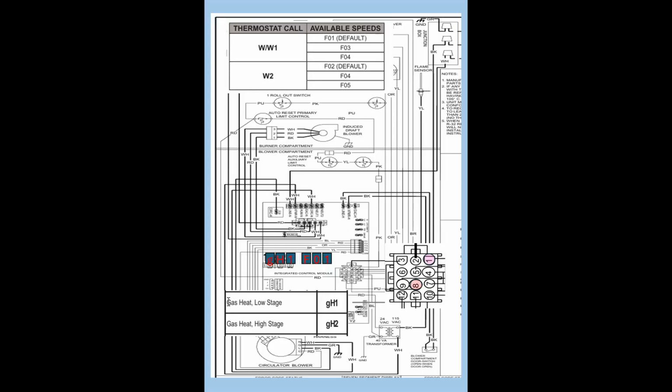The control verifies the auxiliary switches and the primary limit switch are closed by sending out 24 volts on pin 1, a pink wire of the 12-pin connector, through the auxiliary limits and the primary limit and back down to the red terminal, as we're going to see here. Pin 8 on the 12-pin connector. And here we see our 1 and our 8 coming out of this pin connector.